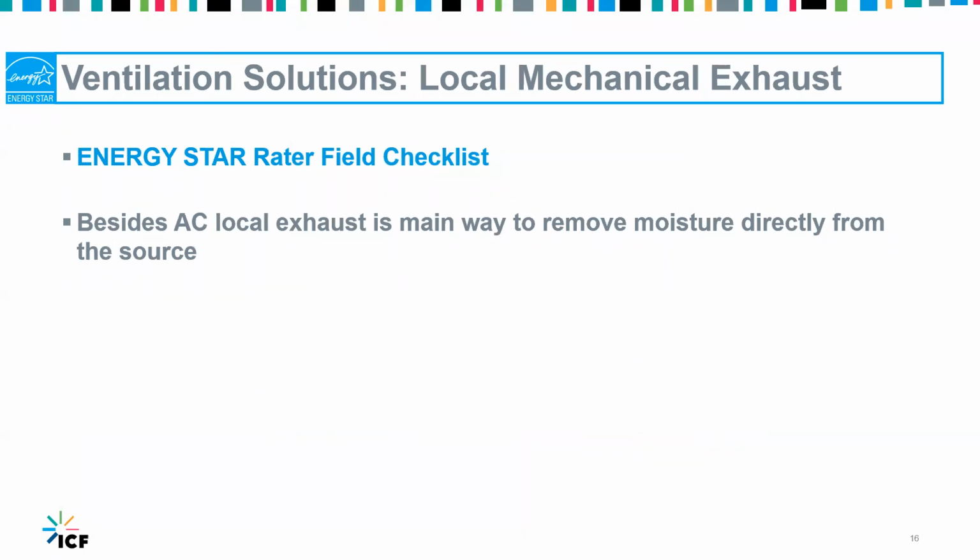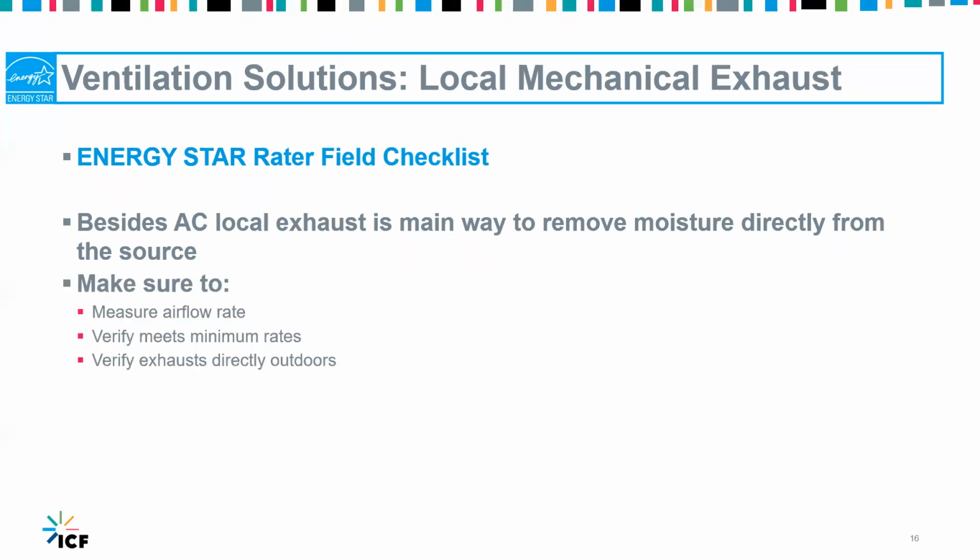So for the next couple of slides, I'm going to talk about ventilation. Before, I was talking about HVAC equipment. The first one on here is local mechanical exhaust. Besides an air conditioner, this is the next way to remove moisture directly from a home, in this case directly from the source, the kitchen or the bathroom. So a couple of suggestions here. Make sure you measure the ventilation rate, that it's meeting its requirements per ASHRAE 62.2, and then verify that it's actually getting that air outdoors.